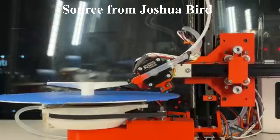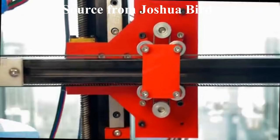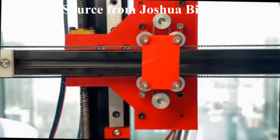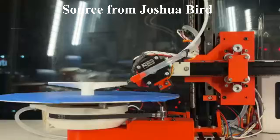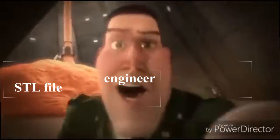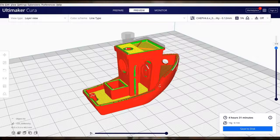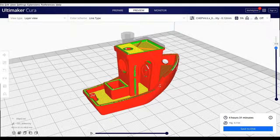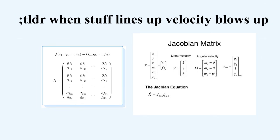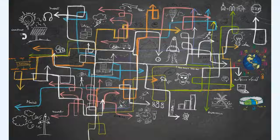However, in turn, we sacrifice simplicity in both mechanical and operational regards. The mechanical side is obvious: cable routing, filament routing, a new motor to drive the fourth axis, but operation is where the biggest hurdle is. Normally, slicing software takes an STL file, slices it, and spits out the necessary G-code in a few seconds. However, this fourth new axis introduces a new variable to account for, and the singularities that come with it. Just slicing along the z-axis wouldn't take advantage of the new fourth degree of freedom. This would mean extra complexity for little gain.